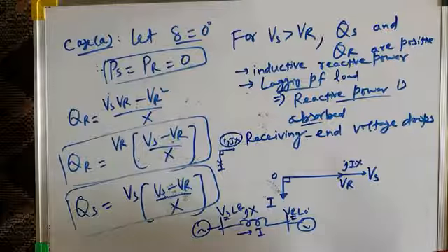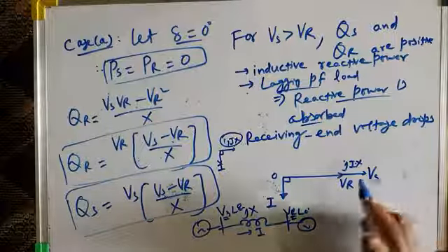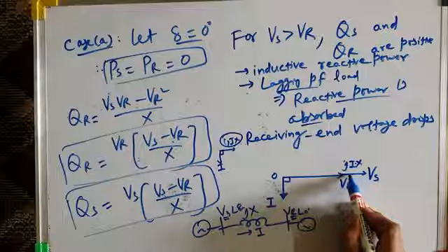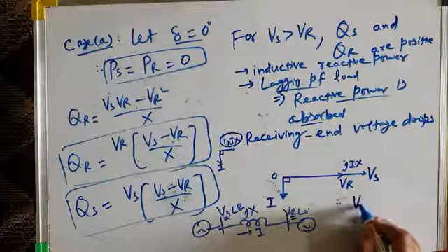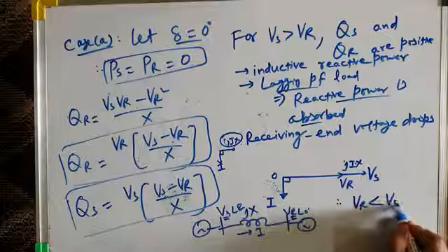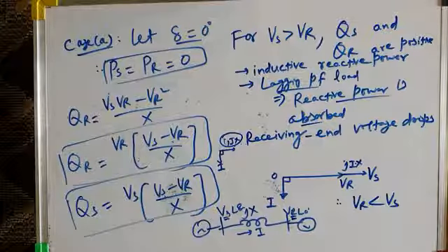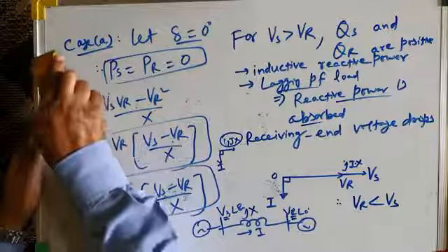Higher is the reactive power demanded by the load, larger will be this drop component and smaller will be the receiving end voltage. So therefore receiving end voltage will always be less than sending end voltage for such a situation. Okay, so this is one point. Another very important point is,